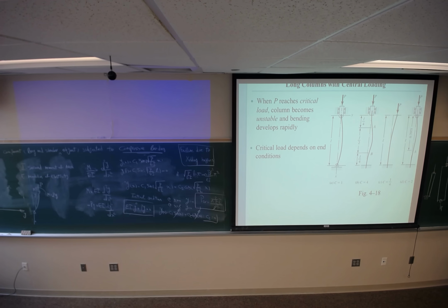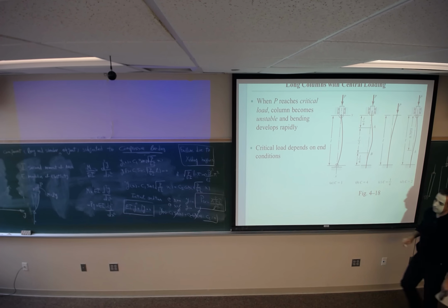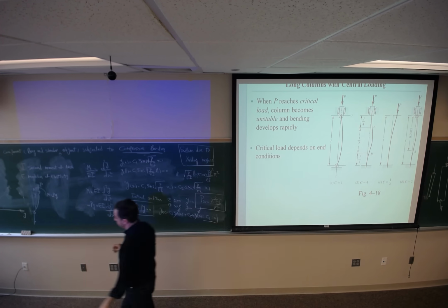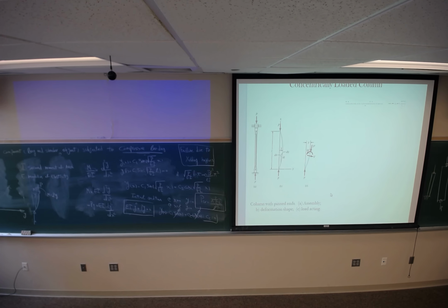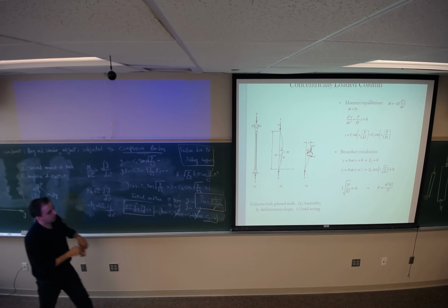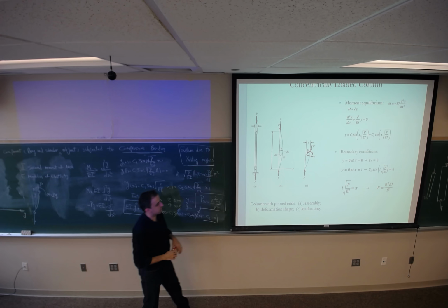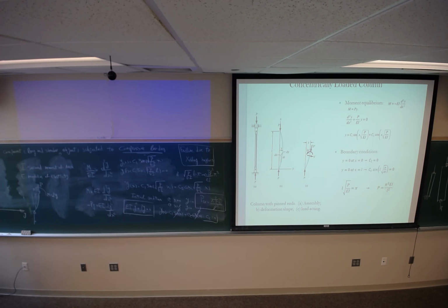And this is the force that I was looking for, buckling. Pi squared EI over L squared. Any question on this?